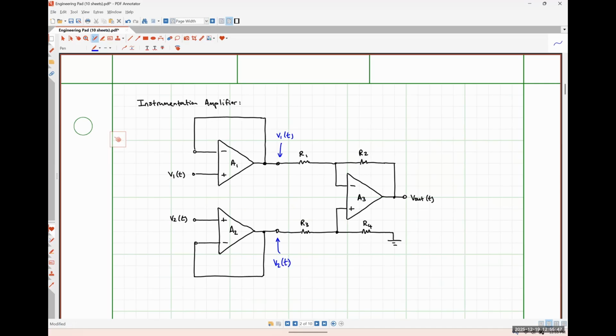Moving on to the third amplifier stage, that should look kind of familiar. Anybody have any thoughts on what that looks closest to? Oscillator? Nope. An oscillator had positive and negative feedback. This guy definitely does not have positive feedback. It's a negative feedback circuit, and it has an input signal applied on both the inverting and the non-inverting sides of the amplifier. We only covered one of those. Differencing amplifier, okay? So this is essentially a differencing amplifier, except that we don't have the same resistors.